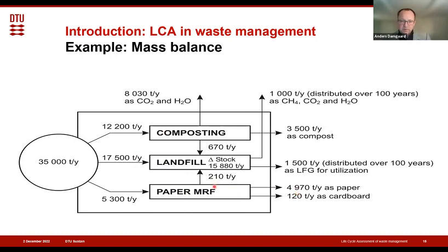But we will also have some impurities that will have to go to the same landfill. In the landfill, we will actually have the buildup of stock. That's why when we see landfills in the areas, we see these mountains of trash that at some point will be covered by soil, maybe vegetation. So we have a delta change to such a landfill, and then we have gas being generated. And there, of course, how we manage the landfill will be important, because do we capture this gas or do we just emit it to the atmosphere?